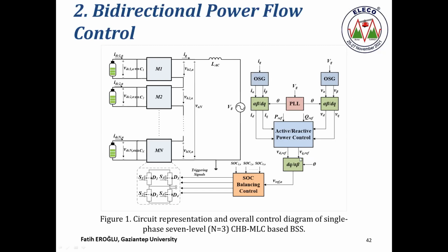The results of power flow control are fed into SOC balancing control, as well as the estimated SOCs of these battery packs. The output of SOC balancing control is used in level-shifted PWM, and triggering signals are obtained for the semiconductor switches.